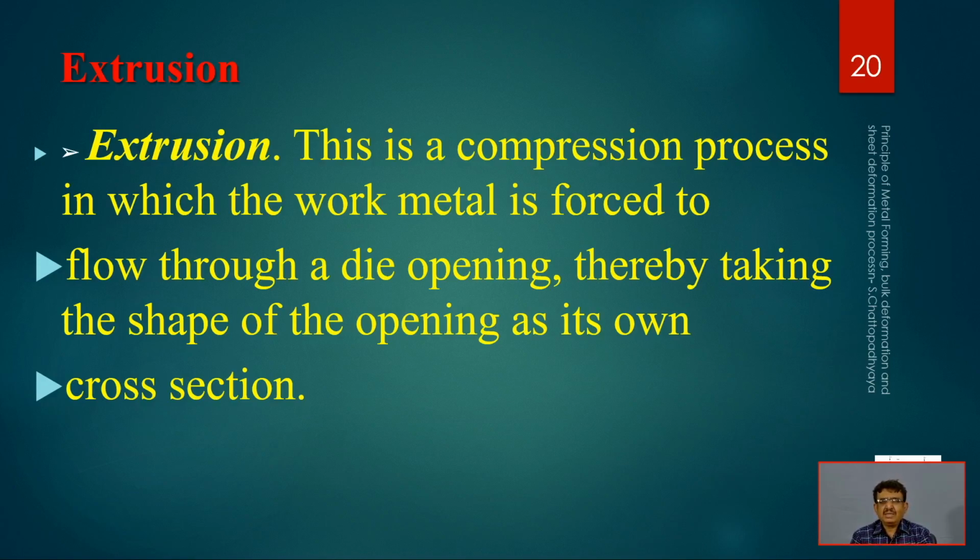But here that is of a viscoelastic material, so that is not relevant here, but we have to produce this extrusion for those metals, and we can generate all those products like pipes, hollow pipes, tubes, solid rods, and other parts in the form of extrusion, but mainly a plunger pushes against the die. And there are two classes, one is direct extrusion and another one is indirect extrusion. So I am not going to discuss that here, because these are all sub varieties and there are different products which are associated with those processes.